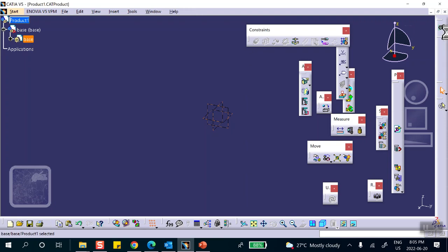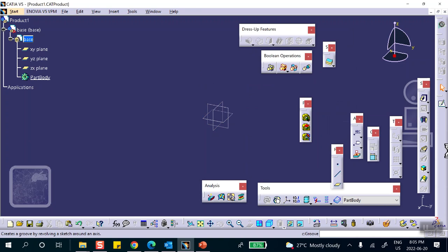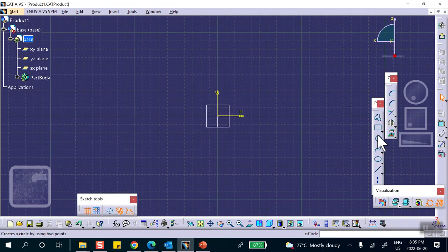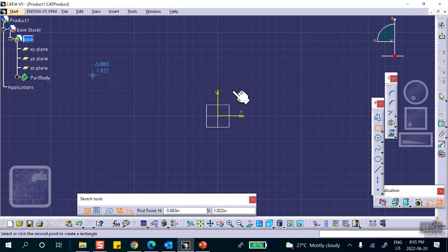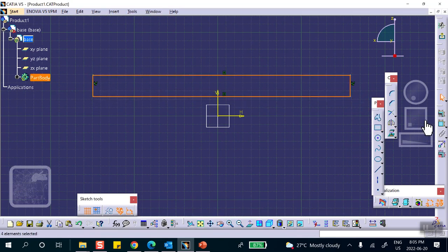That puts you in the part design, and it's a very simple geometry. On a convenient plane, on that vertical plane, I will sketch something that's about maybe 20 inches long. That's going to be basically your track. Let's have an idea how big this thing is roughly.